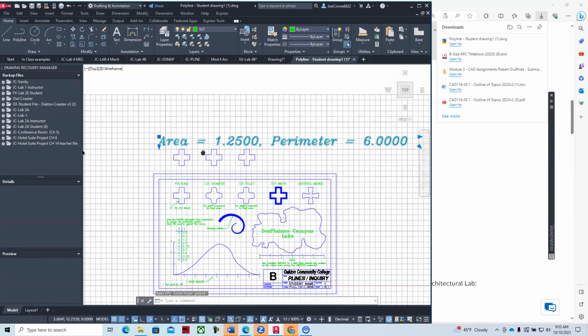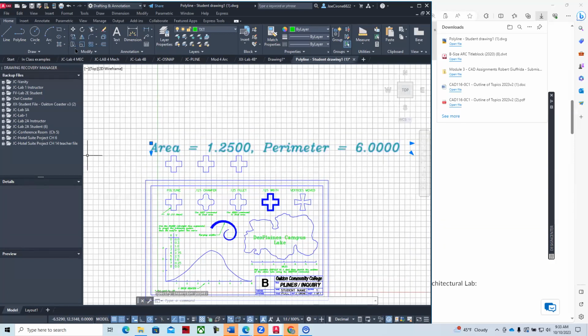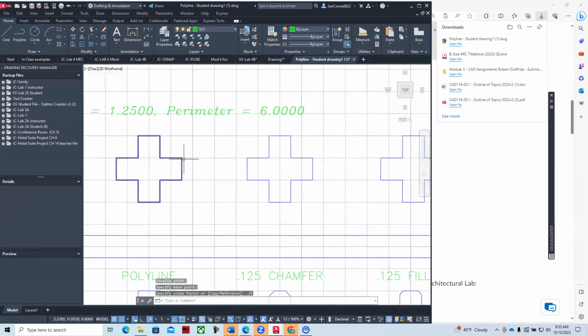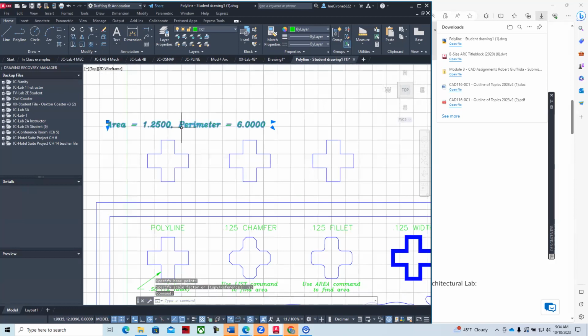And so I'll Control C, and then I'll say Control V, and I'll paste that in the drawing. It's kind of big, and so I'll scale it. And so we can come back over here and we can get the scale command. And so I'll go to scale. And I'll just say 0.25, make it 1/4 of an inch smaller. Still a little bit big, but I think we get the idea. And then it's on the text layer. If I want to darken that up, I can use a little bit darker and then hit escape.